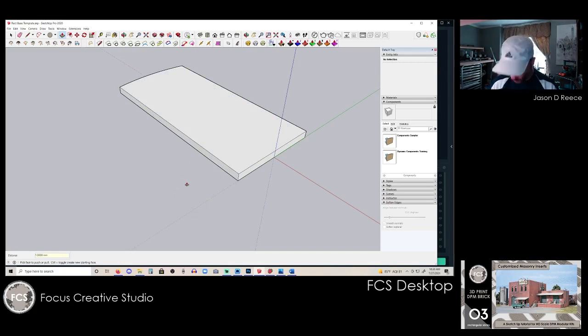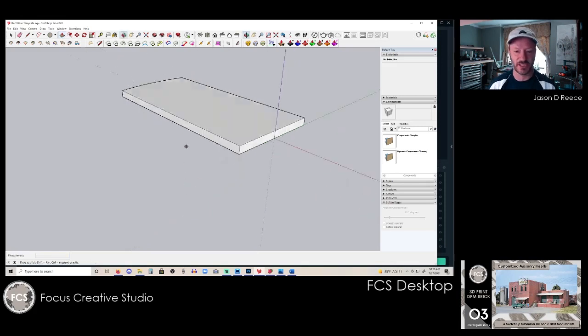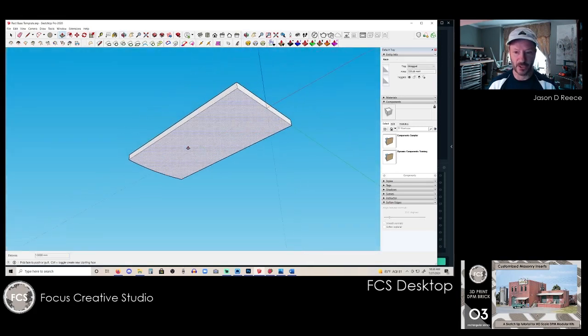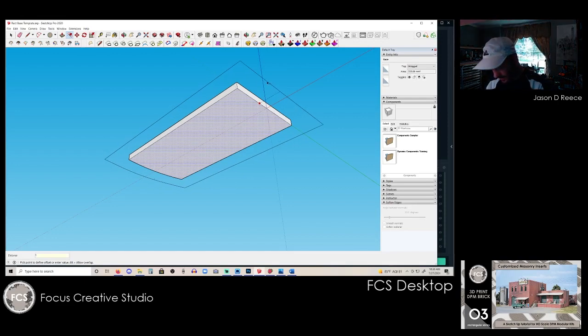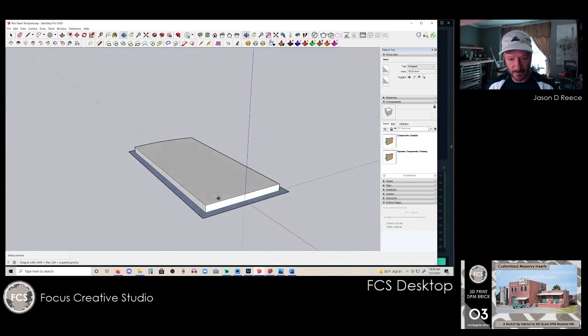And then I've got a portion that allows it to sit flush to the back of the face. There's a lip that surrounds it. So we're going to go to the bottom here, and I want to extend that out. So if I use my offset tool, I'll come in here, select inside, it'll grab a boundary, and then we're going to go ahead and basically offset this whole piece a total of 1 millimeter. So that creates a boundary edge.